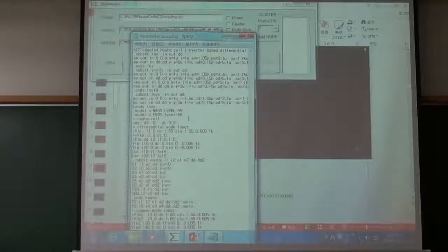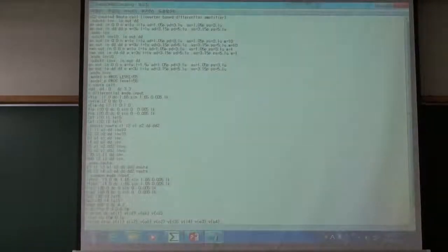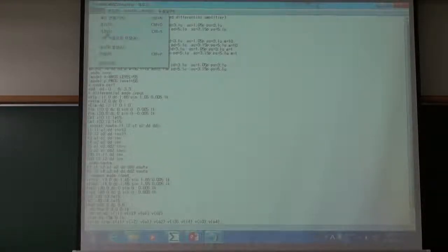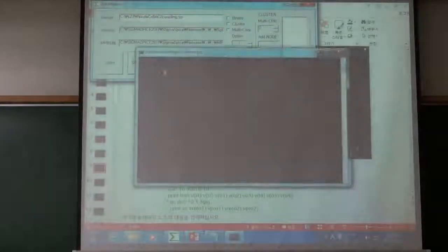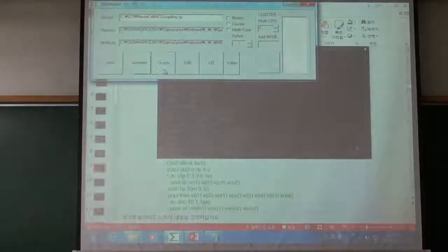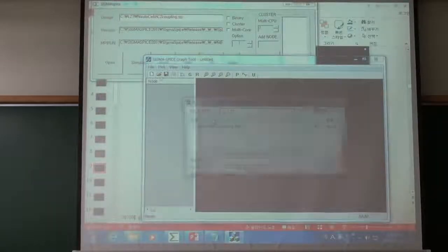All right. Let's go to the VDD2. Okay, where is VDD2? Oh yeah, here. 4.2 is pretty large, right? So if I put like 3.6, my gain will be reduced, right? Differential mode gain, because GM3 is reduced. Okay.